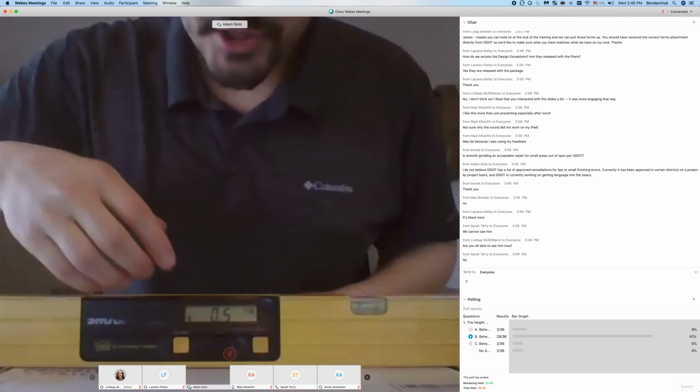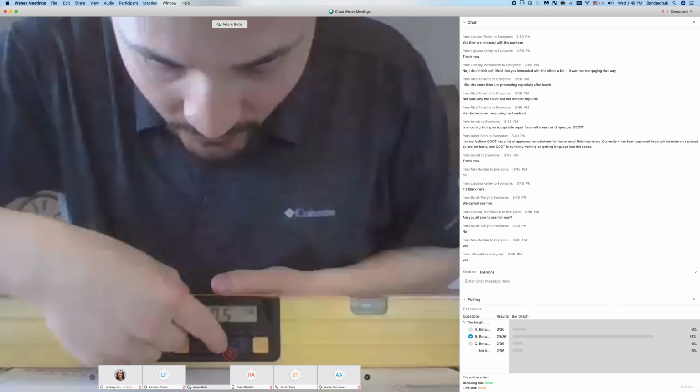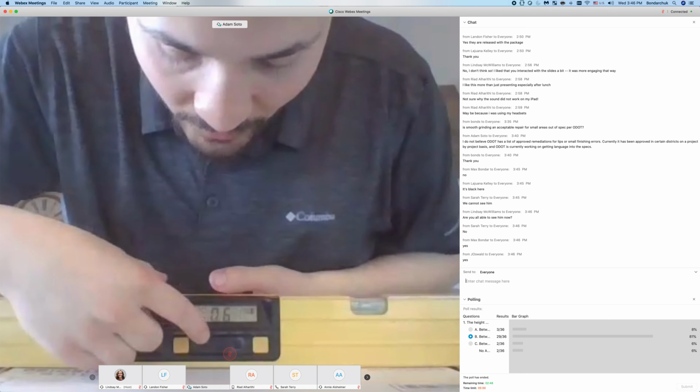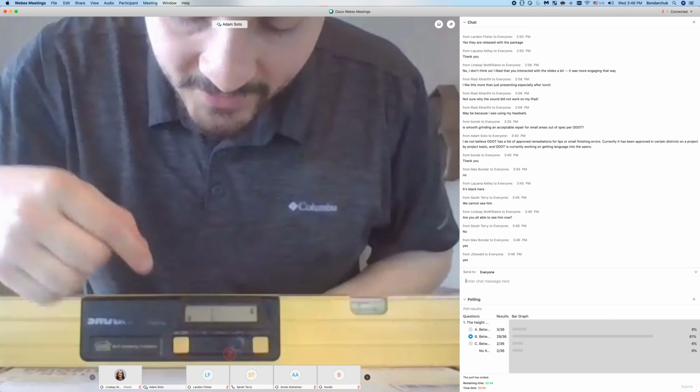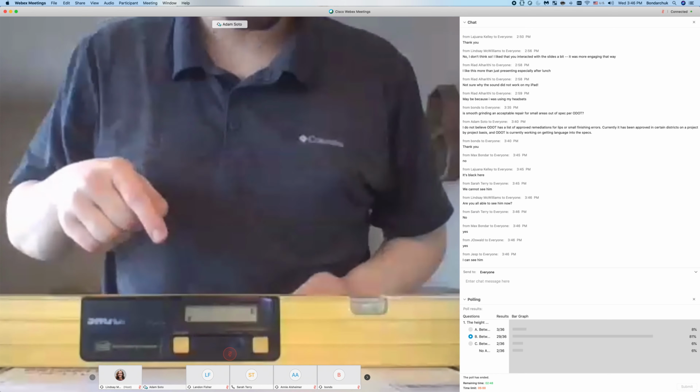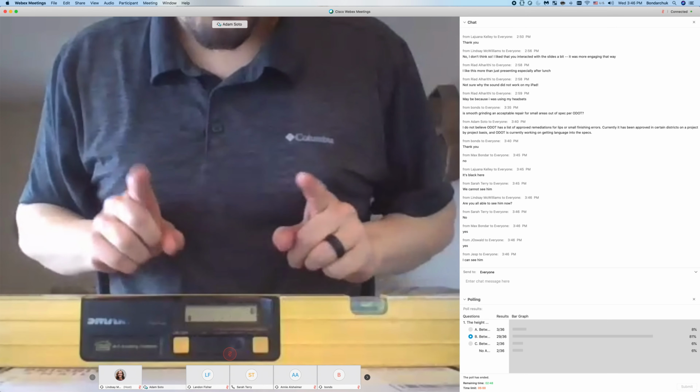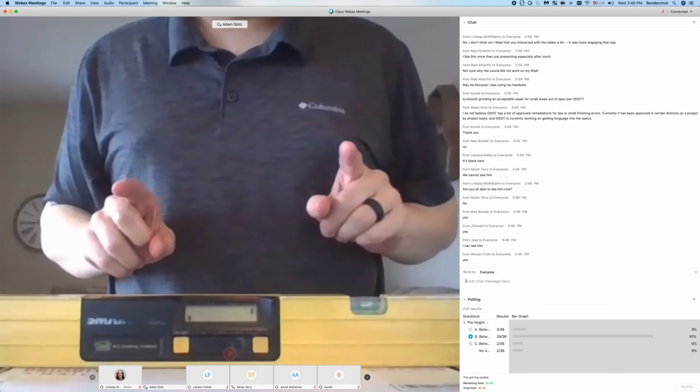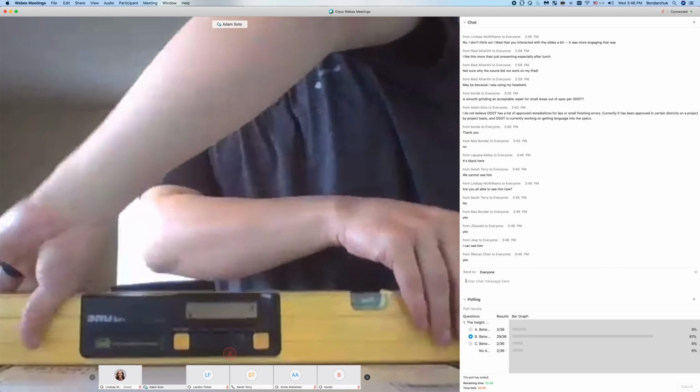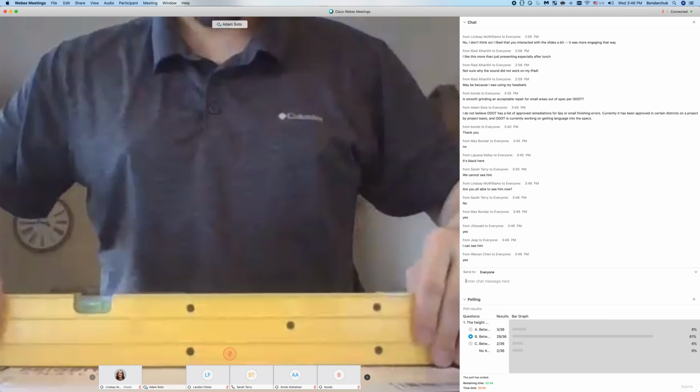So to begin the calibration, we press and hold the middle button on the level, and it's going to say Cal 1 and flash. And now the screen is flashing. We've already taken the first measurement, and so it wants its pair. So we're going to flip it 180 in the same spot.